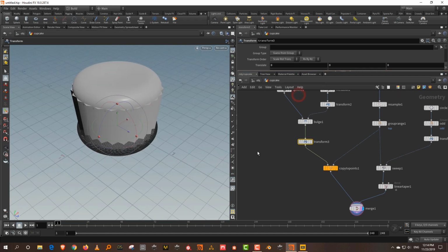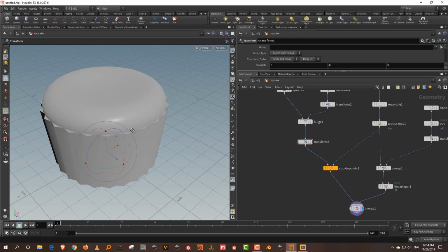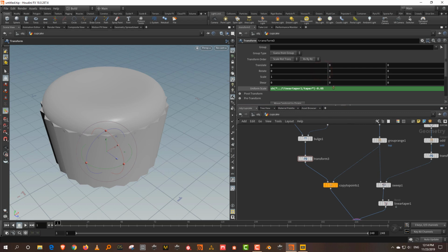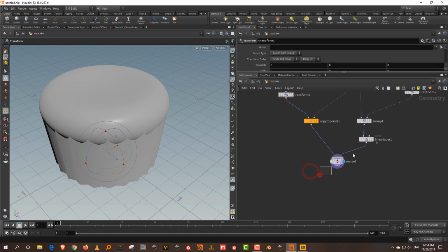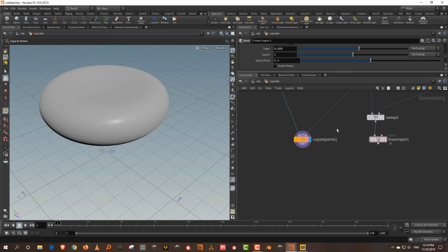Okay, so this is fine, but this still doesn't give us a smooth result that we want. So what you can do instead, or what is a better way to do it, is actually let's just keep it the way it is right now. We'll adjust it later. Instead of using this, and I use this a fair bit, you can use VDBs to do the modeling. Because the great thing about VDB is it allows you to smoothen out objects.